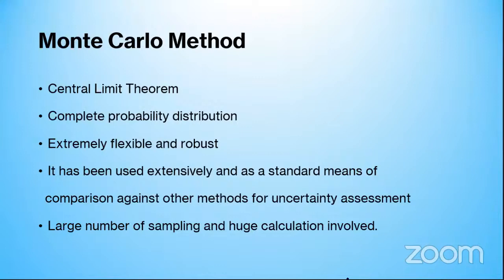Likewise I will divide everything, and then I'll store that particular parameter. I have to combine all the parameters of this particular subbasin, and likewise for all the subbasins. Suppose there are 4 parameters for a particular basin and 10 subbasins, so there will be 40 parameter values. If the number of samples is 10,000, then 40 into 10,000 will be the number of simulations you have to carry out just to calibrate the model, right? So manually it is too difficult.